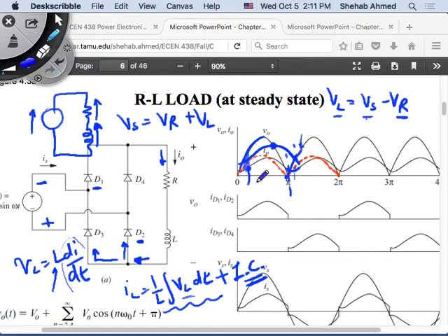Initial condition in the case of my integration is the value right before this step. For example, here, before it does this, my initial condition was here. The voltage was negative, so I went down. Then I go to the next step. This Vs minus Vr became positive. So my initial condition is this point. It's just the time step before. Does it make sense?